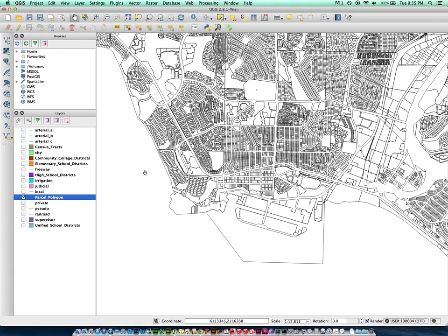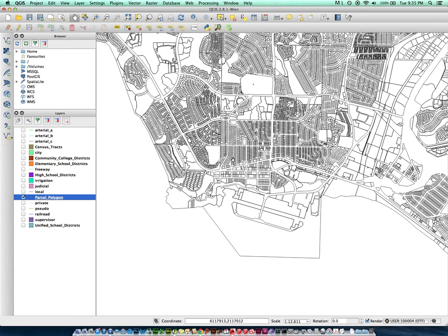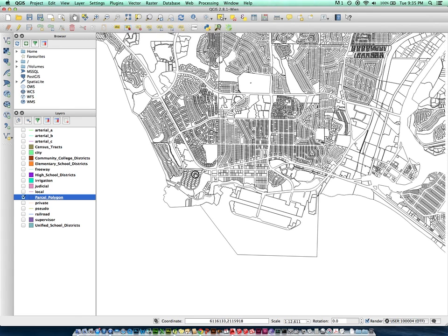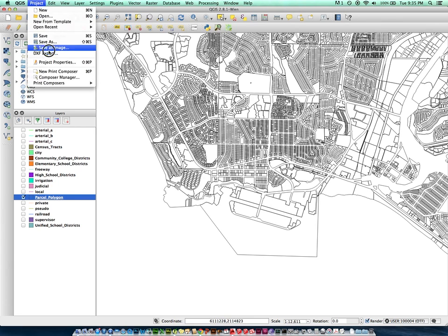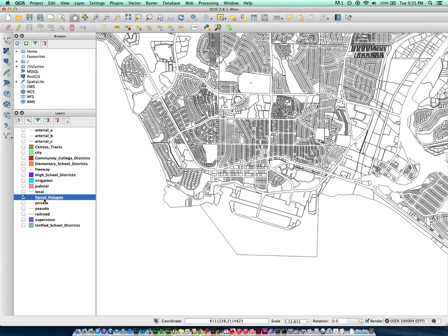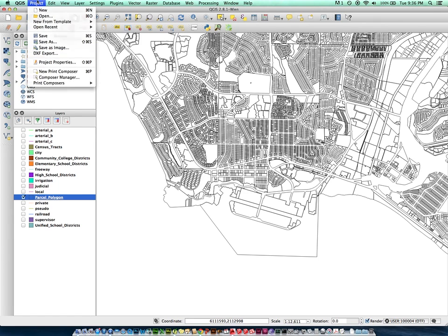So there's a workaround to it that I found, as there's always more than one way to do something. Another problem with the DXF export is that sometimes it actually exports a blank drawing. In this case it shows that there's data there, but I'm not able to see it. Oftentimes during the DXF export it shows a 16 kilobyte file when something should be much larger. That tells you that the drawing is empty. So 16 kilobytes just means that it's an empty CAD file. That's another issue that I found as a bug with the DXF export.